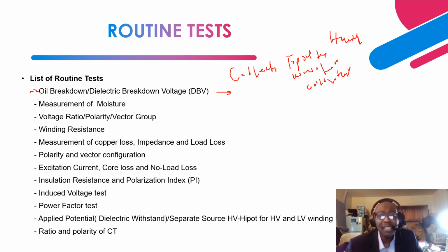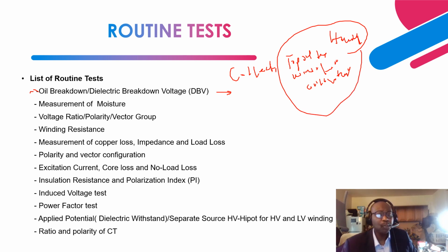These are all the information that you need as you collect the oil sample before you take the transformer offline. Alternatively, you can collect the oil sample immediately after you de-energize the transformer. Either way works, but it shouldn't be longer than when you take the transformer offline.